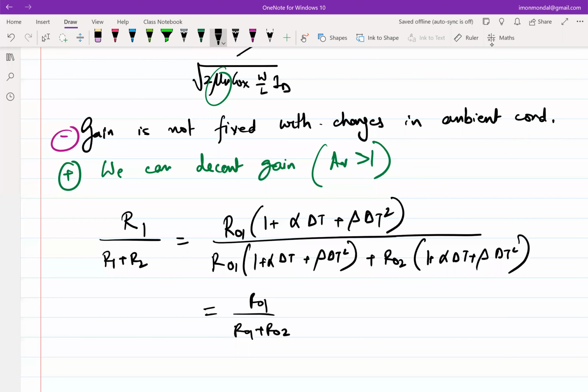But that is actually a design problem which IC designers have to take care of when we design ICs. You have to make sure that whatever you are designing for tracking closely, you place them very close to each other, so that whatever bad things happen to the neighbor, the same thing happens to me. Or maybe the other way around.